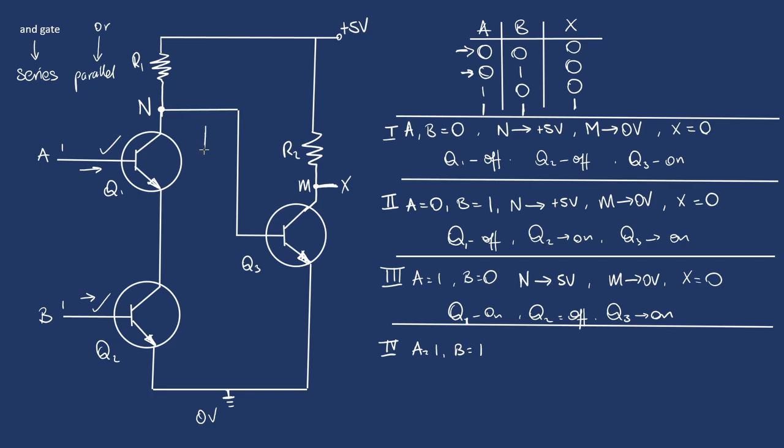Okay, so that means we have a short circuit, a closed circuit, and a ground connection. So this is one full electrical path, meaning that N can be grounded. Okay, so finally N gets dropped to 0 volts. Okay, remember now we have a closed path from positive 5 volts to R1 down to ground. So since N is at 0 volts, then no current enters IB. Okay, and this guy becomes an open circuit.